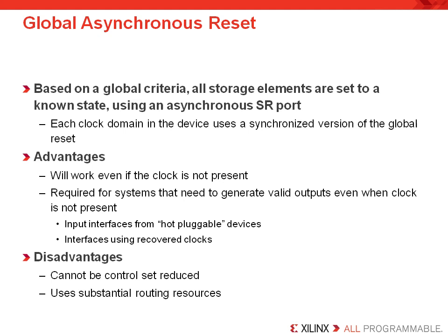Now this slide is talking about using an extra global reset that is asynchronous. So you need to recall that in the previous recording we mentioned that if this is asynchronous, it needs to be synchronized so that it does not cause your circuit to go metastable. Now this is simply based on your global design. All storage elements will be set to a known state using an asynchronous set or reset port. And note, it can only be mapped to the flip-flop set or reset port.